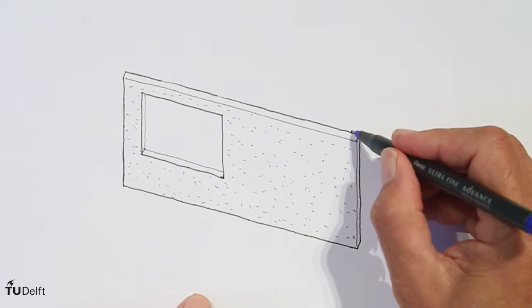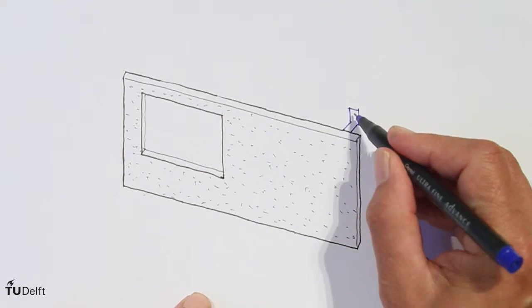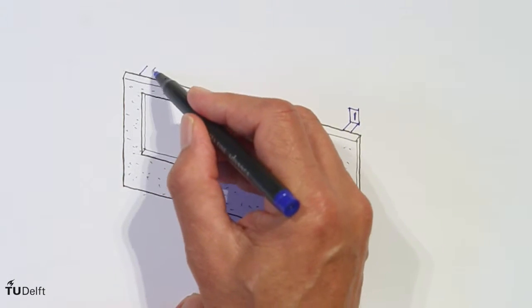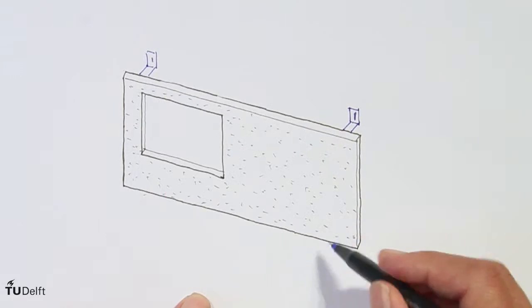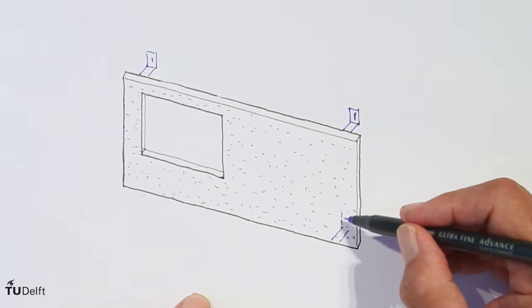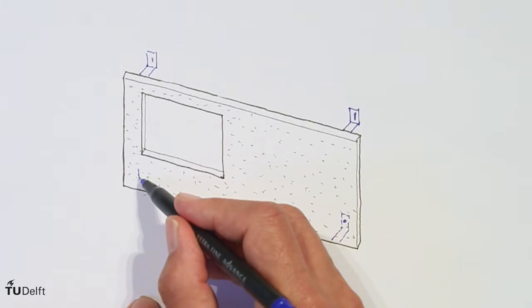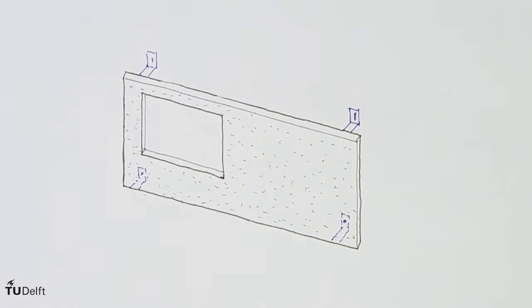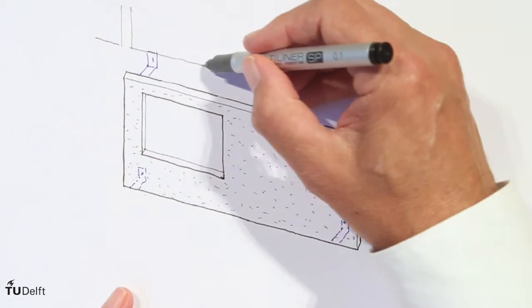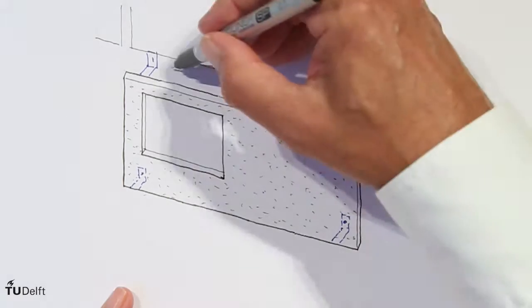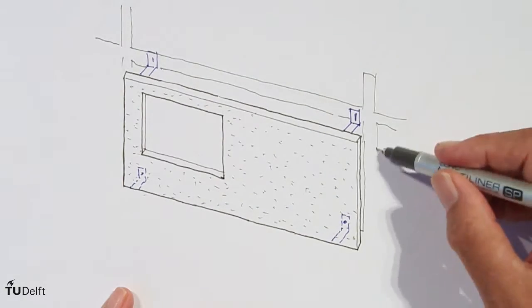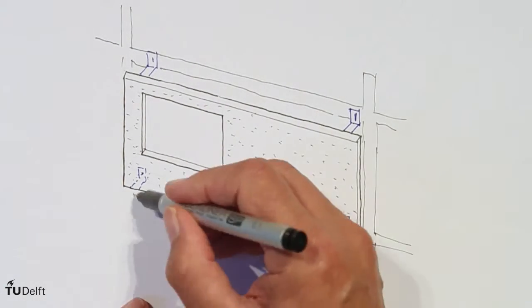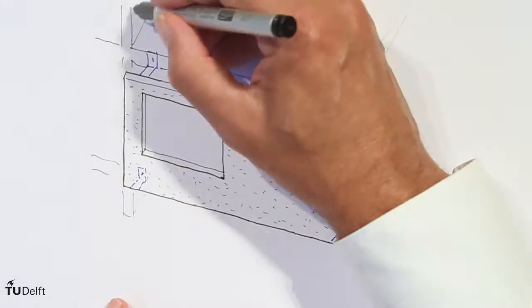The third type consists of a plate mostly in concrete, although also glass fiber reinforced concrete or polyester might be used. The element contains the openings for window frames. The plate is anchored on 4 points, by preference to the main load-bearing structure, not to the inner leaf. But in case the inner leaf is a concrete slab too, the outer slab can be connected to the inner slab.